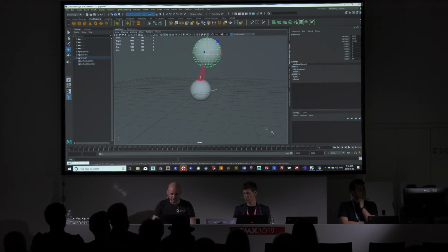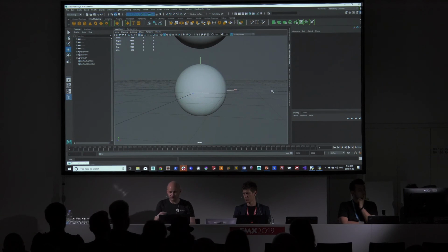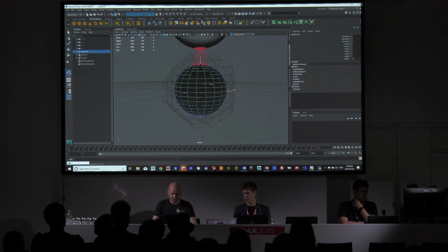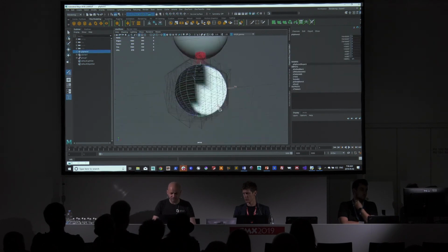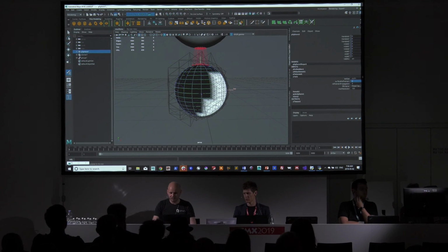One of the other features, Andy showed the overall TET size that you can adjust interactively. A lot of times you'll have situations where you just want more TET resolution in one part of the mesh, but not in others. So we have added, like he touched on, paintable attributes on most everything. With the TET mesh, you can go in here and just paint where you want smaller TETs. And if you want to adjust it, there's a surface refinement number here, which you can think of almost like a subdivision level. If I put that to a higher number, the TETs get smaller just in that area. So that's a nice way to help balance the speed versus the frequency that you want.